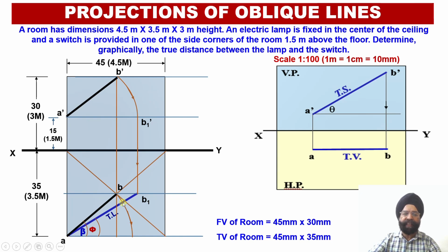and rotate this point B in such a way that this rotation must proceed up to the locus line corresponding to the point A, such that this point A and this point B2. So since this is the second rotation, the name of this point happens to be B2. So AB2, which is the apparent length in the plan, we can check over here, AB2 happens to be parallel to the vertical plane.